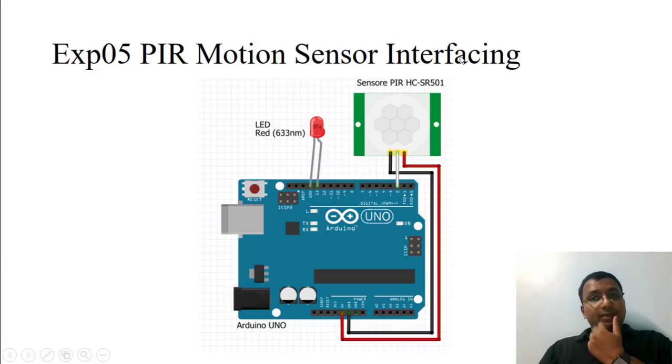The PIR sensor range is up to 15 feet. Technically, ideally it's a 15 feet range, and the drawback of the PIR sensor is it can sense any motion directly. Suppose you have attached the PIR sensor in your parking slot, and there are some plants and because of air the plant leaves are moving, then it will detect that as a motion.